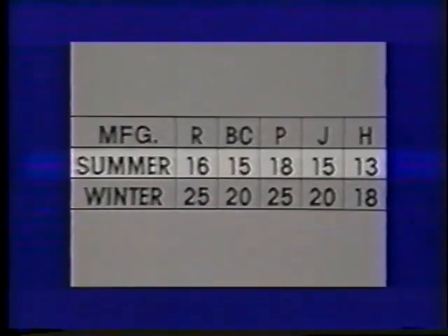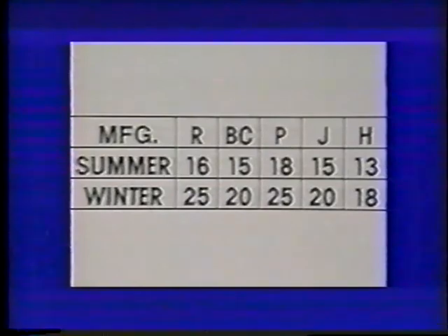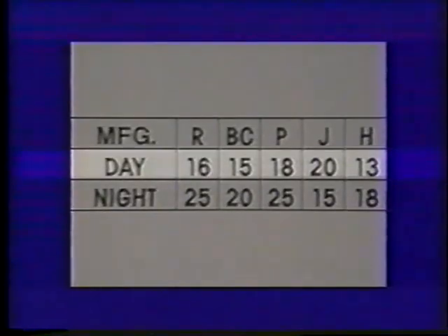The lower pressure is nominally supplied to a summer-winter thermostat when the demand calls for cooling and the system needs to be switched to the summer cycle. A higher pressure is supplied to the thermostat when the demand calls for heating and the system is to be switched to the winter cycle. In day-night applications, the lower pressure is generally used in the day cycle and the higher pressure for night cycle operation.